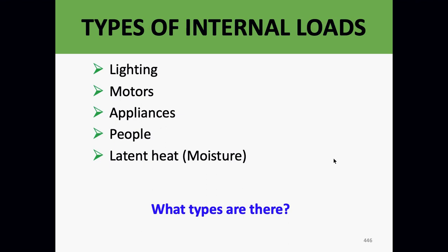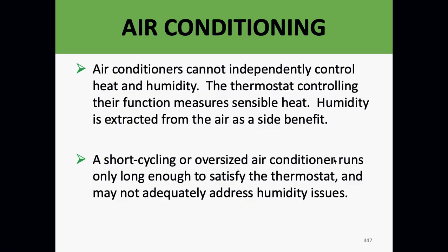Internal loads: lighting, motors, appliances, people. All part of the internal loads. Now, there's a lot of other things that could affect this, especially in a house, but we can't size the equipment for them. We just have to have enough of what I call leeway, or a sort of borderline fudge factor, because you have to account for things like computers, cooking, bathing, showers, hair dryers, stuff like that. You don't know whether they're going to be used, or how often.